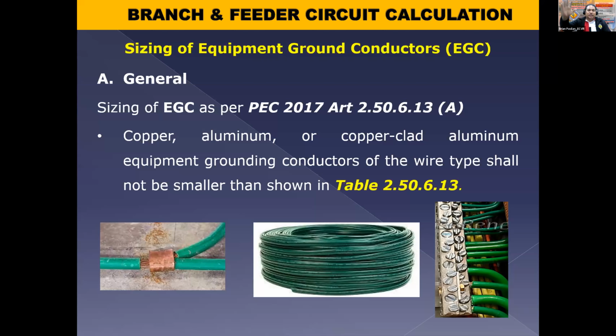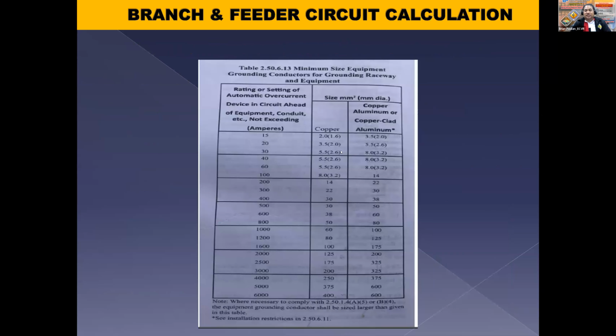Especially for high-rise buildings, yung mga malalaking industrial complexes, no? Yung table natin sa PEC may not be enough na. Yung table kasi sa PEC natin may limitation ito, no? But it can simplify our design. Like for example, this one, instead of computing, meron na siyang specified minimum size of ground conductor for a certain rating of circuit, like 15 amperes.